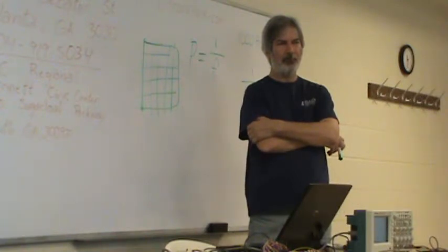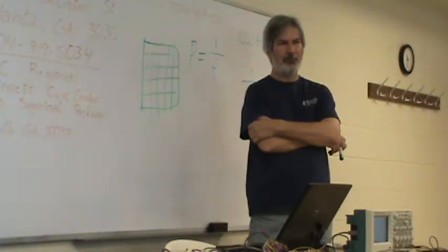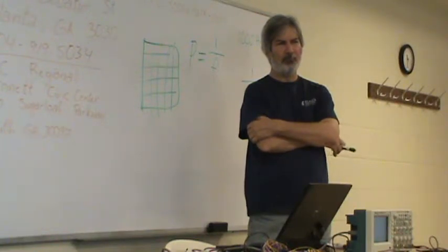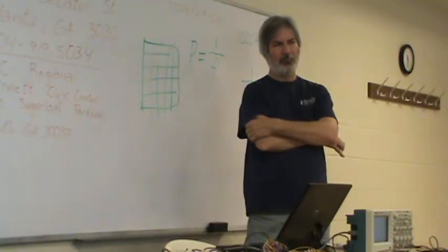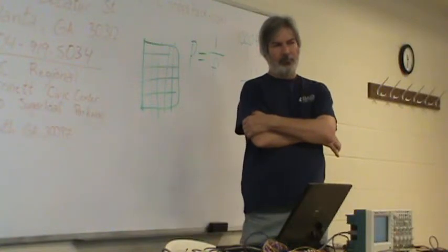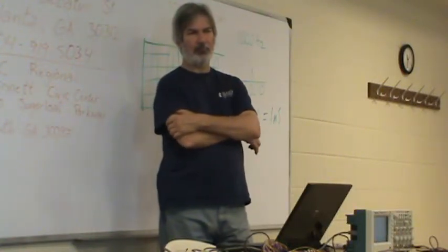Auto, even if there's no trigger at all, it'll say, okay, there's no signal for so much time, and it'll sweep again. It just sweeps by itself. And when a signal appears, it'll lock onto it and try to synchronize with it. But if there's no signal, it'll continue to sweep. Or if there's no signal large enough to trigger, like a really small signal, it'll still show you some unsynchronized wiggling on your trace, but it may not be synchronized.